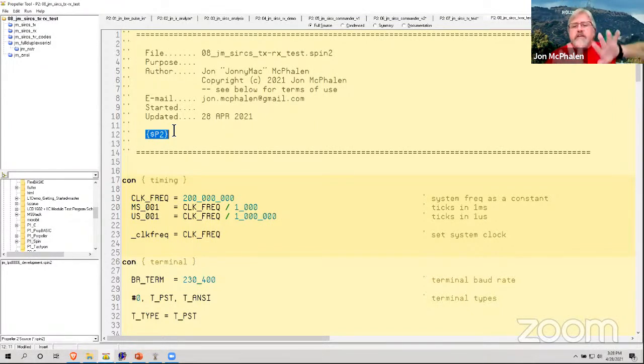And like I said, it's actually a 2-stage FET. If you turn on one FET, that does modulation. If you turn on the second FET, that shorts out the second resistor. So if you want high power, you turn on the second FET, that shorts out a resistor, and the first FET does the modulation. If you want low power, you turn off the second FET, and that gives you 2 resistors in series. It's not a circuit I designed, somebody else did. I put better parts into it, but that was taken from the original tagger. At first I was looking at it trying to figure out what they were doing, and then it made sense because, again, in the tagger